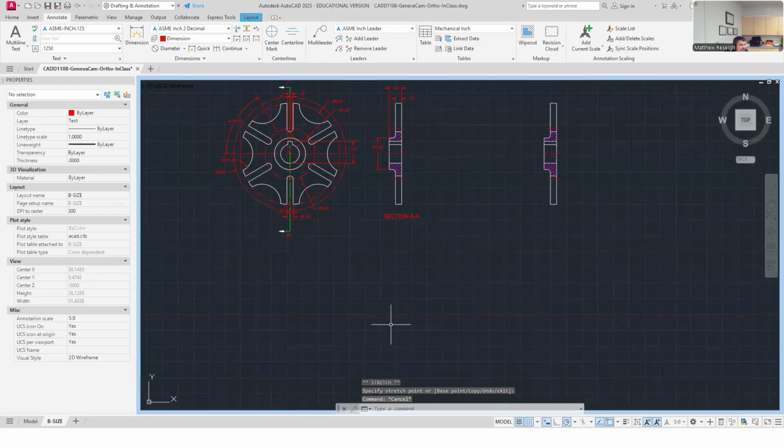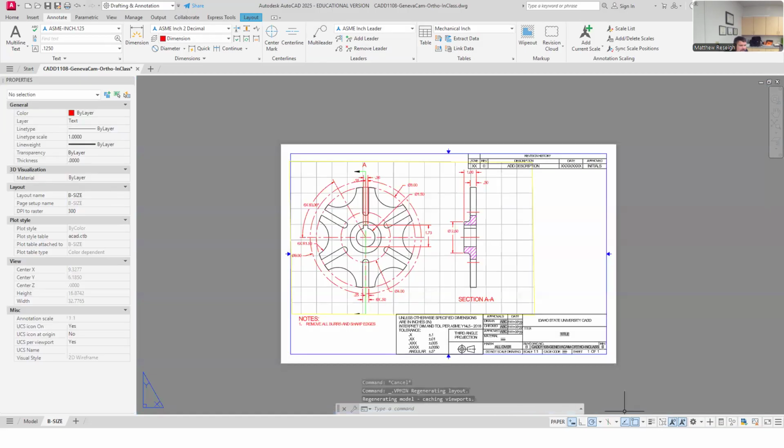So what I've got to do now is clean up. Essentially when I come back out to here, I just need to pull my cutting plane lines. Always make sure it just clears everything. There's no specific distance that has to go out away from everything. I just make sure it clears. So I'll decide that once I've got my dimensions placed a little more accurately, like the spacings on them.